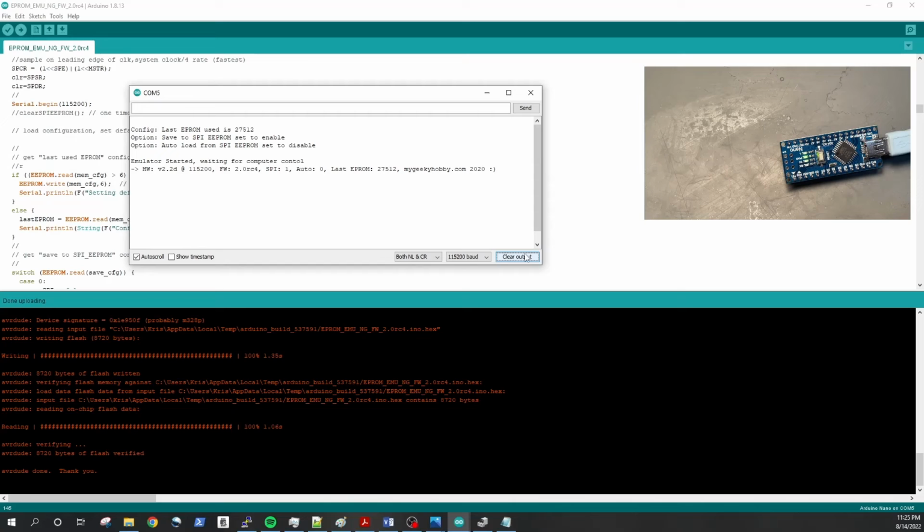But if you know that this happened before, and if you quite often use those Nanos, it might be worth just purchasing a set of those CH340s for the situation where you have to repair one of those Nanos. They are becoming more and more expensive because of the shortage of the chips. So suddenly it's worth occasionally to try and repair those modules.